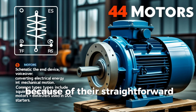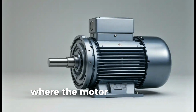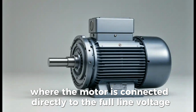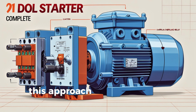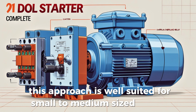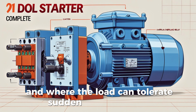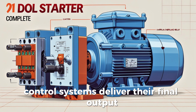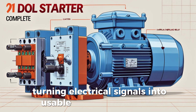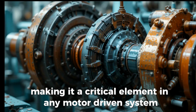Because of their straightforward operation, squirrel cage motors are ideal for DOL starters, where the motor is connected directly to the full line voltage without any soft starting or speed control. This approach is well suited for small to medium-sized motors where high inrush currents are acceptable and where the load can tolerate sudden starting torque. In summary, the motor is where electrical control systems deliver their final output, turning electrical signals into usable mechanical energy, making it a critical element in any motor-driven system.